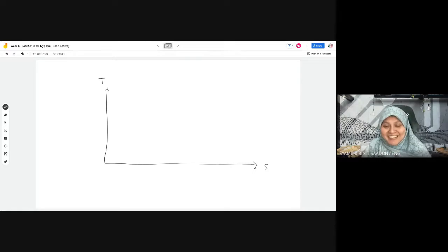Okay, again, sorry, I will show you how to locate first the point in a TS diagram. It is slightly different than previously because in this one the fluid is totally air. So that's why we use a compressor, we don't use a pump. A pump is for liquid. So here it is air, and the location in the TS diagram is slightly different.